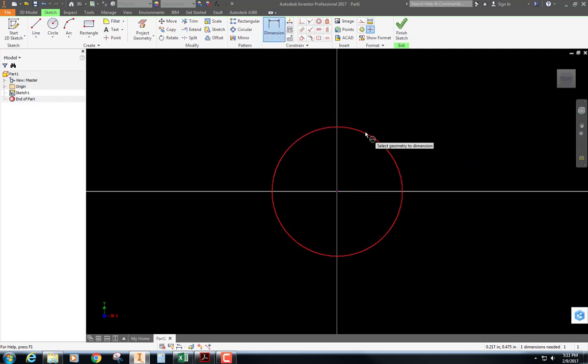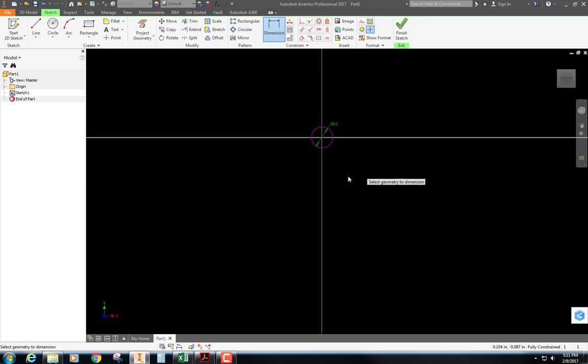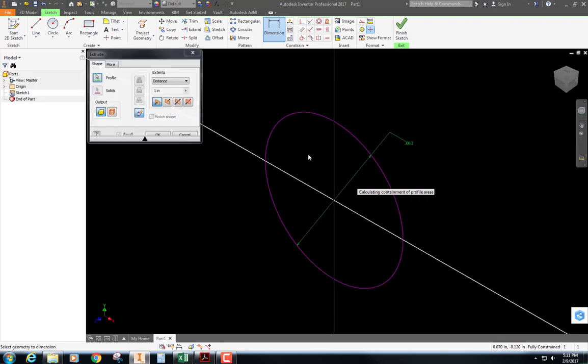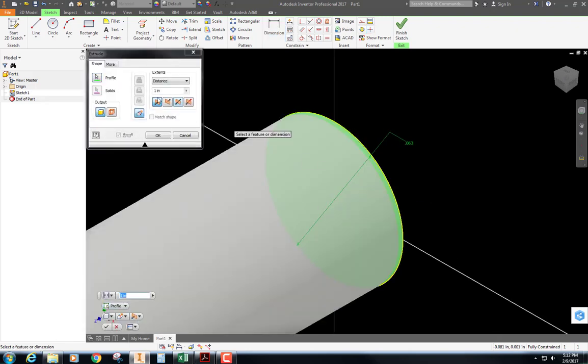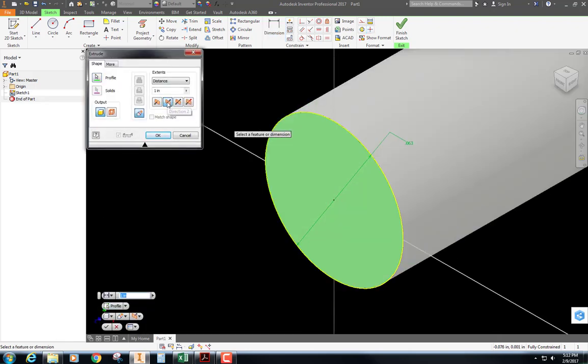and that messed me up. So let's do this again. Okay, so there it is, and now when I hit E for extrude, it's going to select inside that. I like to push my geometry away from my sketch, and now I'm going to put LE in for my parameter, equal, and then the length of that is 0.24. It's a lot easier just looking at my spreadsheet now and putting these things in.